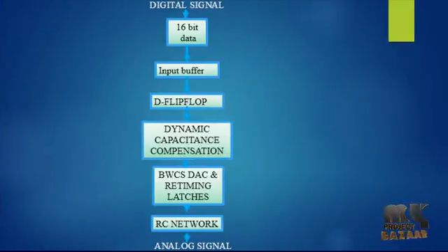The flip-flop is important for clocked flip-flops, as it ensures that inputs S and R are never equal to 1 at the same time. The D-type flip-flop is constructed from a gated SR flip-flop with an inverter added between the S and R inputs to allow for a single D input. Then the single data input labeled D is used in place of the set signal, so this single input is called the data input. If this data input is held high, the flip-flop would be set, and when it is low the flip-flop would be reset.